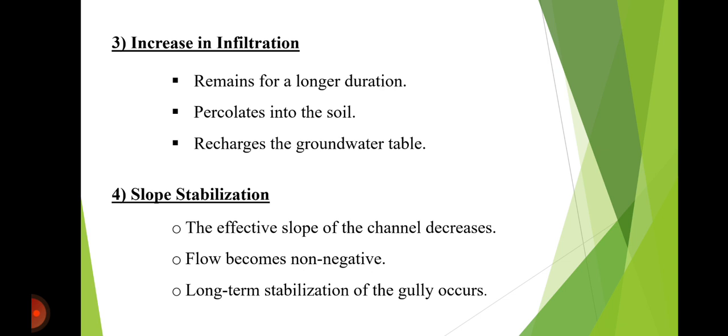So the basic principle of a check dam is to reduce the energy of flowing water by slowing runoff and allowing sediment deposition and infiltration. Check dams help control soil erosion, conserve water, stabilize gullies, and protect the downstream areas.